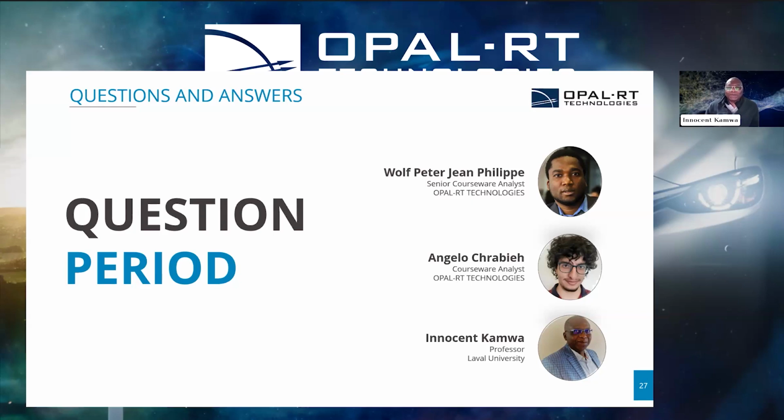I think generally students will be tempted by RT Lab because they have prior experience with Simulink. So they will say, starting with RT Lab is quite easy. That's what they will believe. But unfortunately, it is not true if you have a complicated system, if you have high switching devices, if you have power electronics. Very quickly, RT Lab will become slow. RT Lab will reach the limit. For instance, it will not be able to perform real-time simulation because the system is too complex for it.